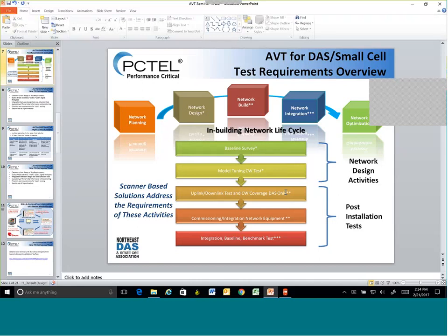What we've been asked to add, and are in the process of adding now, is to integrate a test mobile to do some basic tests. The theory goes like this: if your downlink measurement is good and meets your design, and the interference and noise look good, then when a phone is interacting with the network equipment, and everything has been adjusted and levels have been set, you expect it, during the course of using it, like downloading a file or having a call up, to have a certain transmit uplink power. You expect it to be within a tight range.